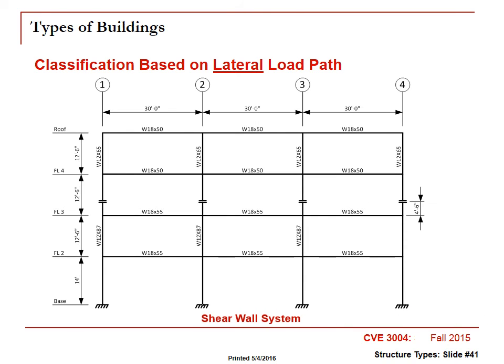Okay. If we had a shear wall system, now you'll notice this frame doesn't have any of those designators like for moment frames, or any diagonals. What we might have, interior to the building or on some exterior wall, is a stairwell or an elevator core, something that is actually reinforced to accept lateral loads and to transfer those lateral loads down to the soil.